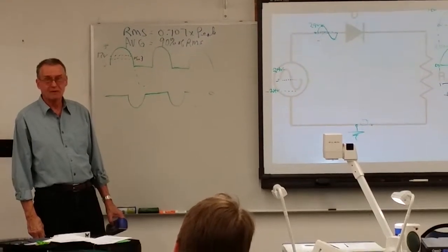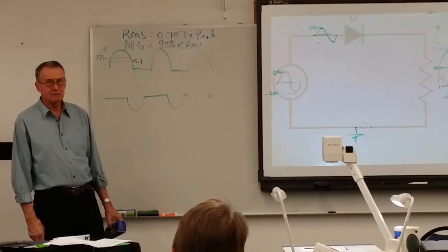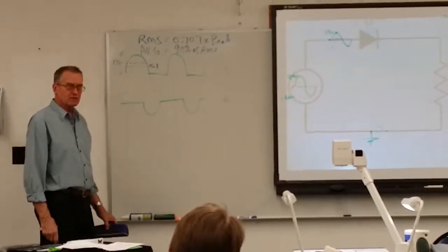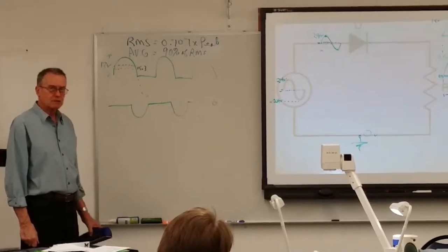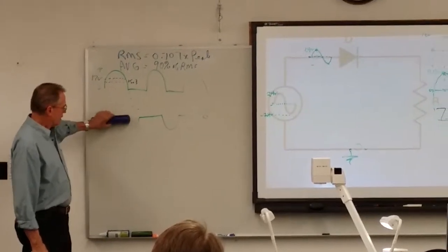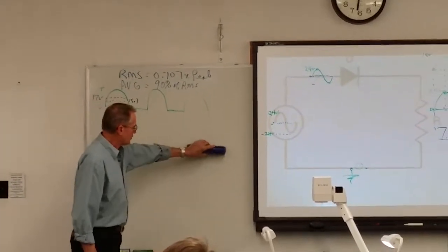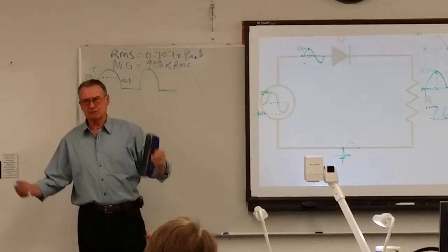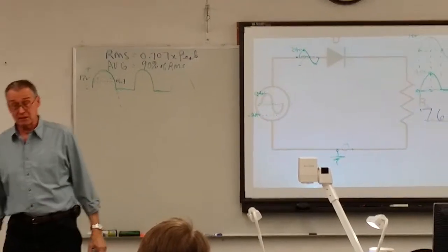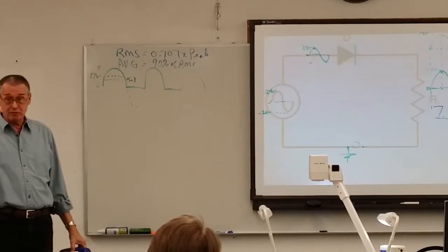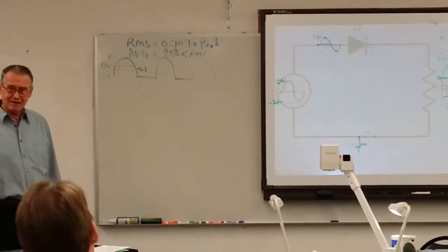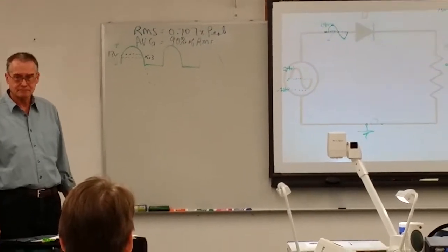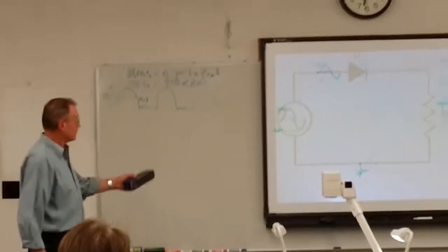6 amps wouldn't take long at all to charge a 12 volt battery. Yeah, 6 amps is pretty good. You can charge them up in an hour or two. But you can't overcharge a car battery with a limit of 3 to 5 amps, or even probably 10 amps, because they're not going to draw any current when they're full. As they get more and more charged, they get higher and higher resistance. The current gets down to almost nothing because the current's dependent on the load, right?